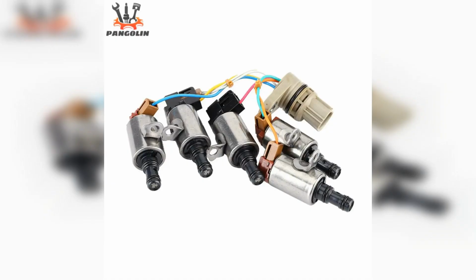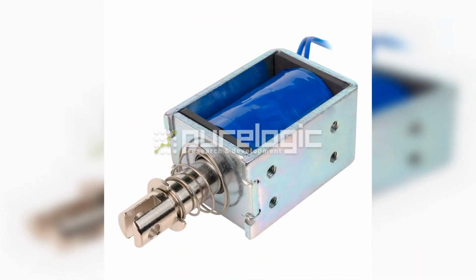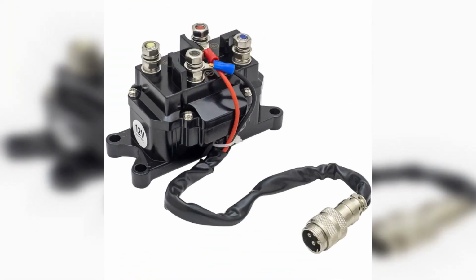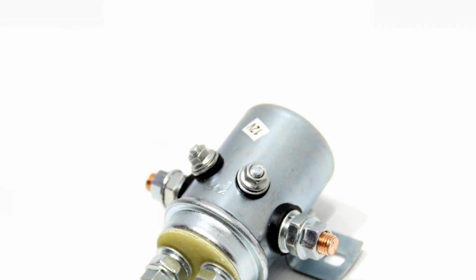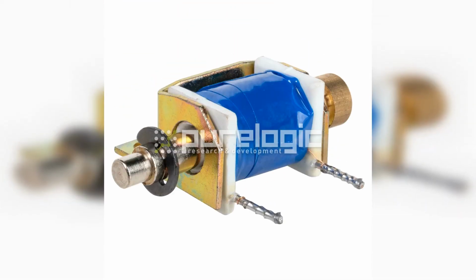In conclusion, addressing fault code P076C, which indicates a shift solenoid performance issue, requires a systematic approach. By understanding the symptoms and conducting thorough diagnostics, you can pinpoint the root cause of the problem. Remember to check the solenoid's electrical connections, inspect the transmission fluid, and consider any potential mechanical issues. If you find yourself needing to clear the code manually, following the proper steps can help reset your system. Always prioritize safety and consult a professional if you're unsure.